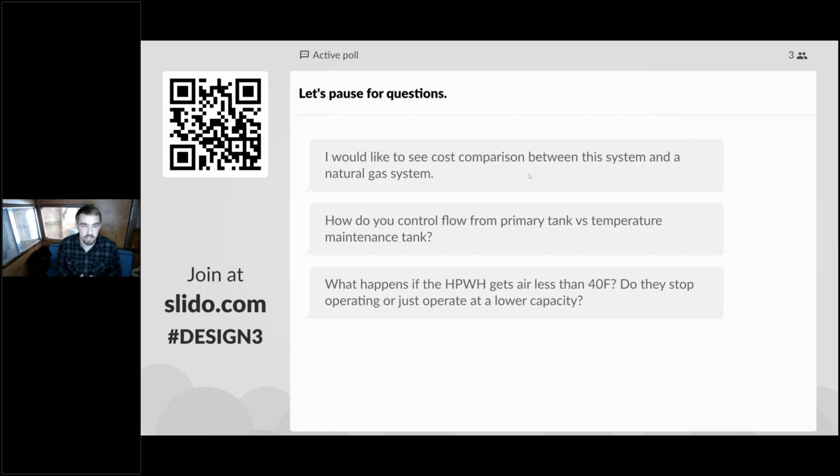One is if this is the last system using gas, the domestic hot water system, then you may be able to take the gas infrastructure out of your building completely if you implement an electric heat pump water heating system, which makes it pencil out really well. It gets a little more muddy if you're just comparing a gas boiler to a heat pump water heater, and there are different sizing methods and capacity requirements assigned to those.